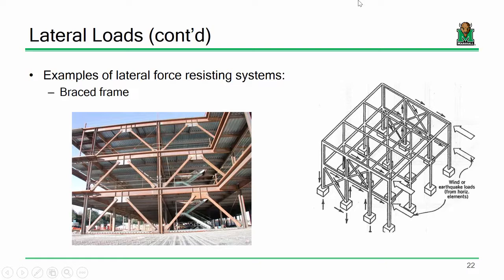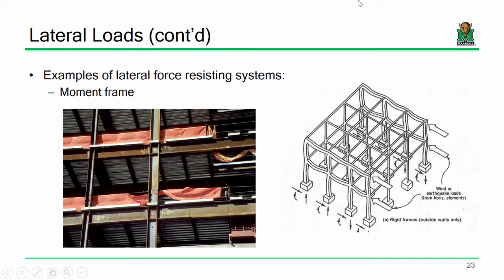Okay. Now, braced frames are one of the two primary ways that we go about this in steel structures. The other way is to use a moment frame. Moment frames have advantages and disadvantages, and the same thing's true with braced frames. With a moment frame, you don't have these large triangular braces in the middle of your base. So it makes your architect and your client happy in terms of keeping open window space and open ingress and egress space and things like that.